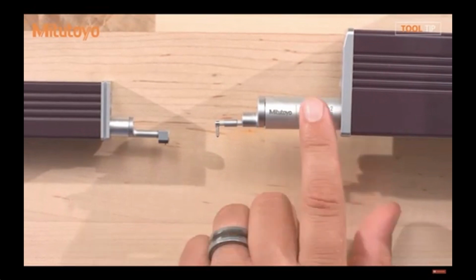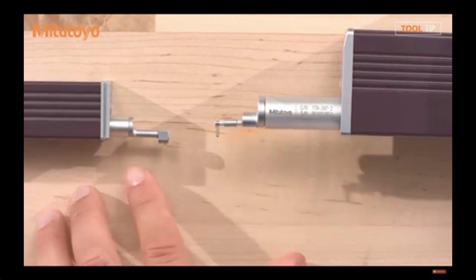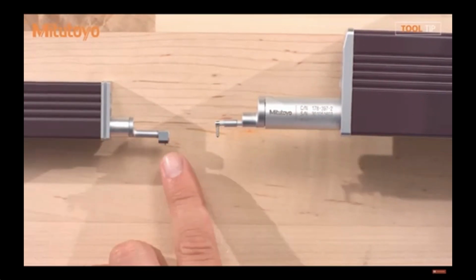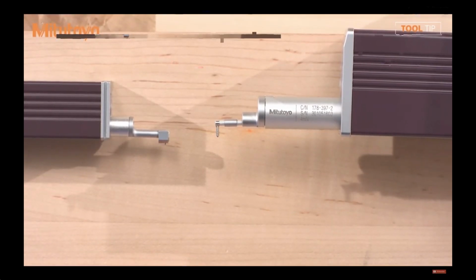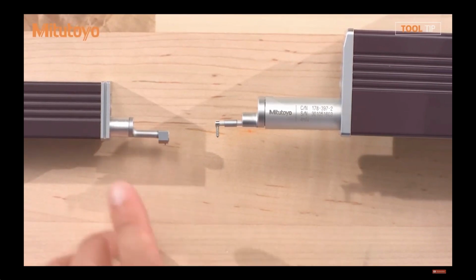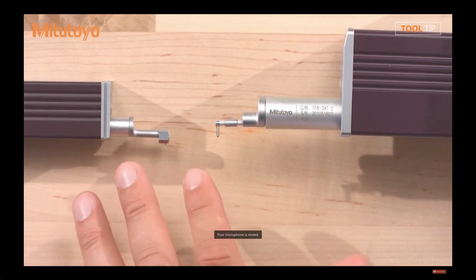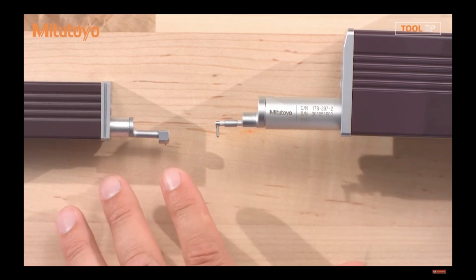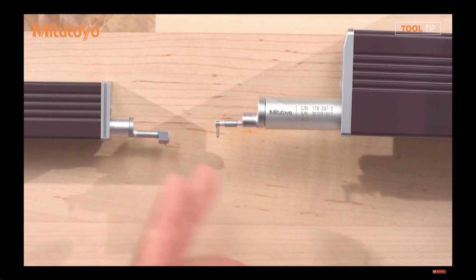Now, this is a skidless system, as I mentioned. The skidded system is very similar, except you'll notice that the stylus and the detector are all one piece here. So I still have the stylus that's protruding out from the detector, but around it is a housing, and that housing is what we refer to as the skid right here. So what's the purpose of the skid? The skid is going to act as a mechanical datum for the surface that you're measuring. On a skidless system, that datum is actually inside the drive unit. So you're going to find that most entry-level systems are going to be the skidded unit with the housing around the stylus.